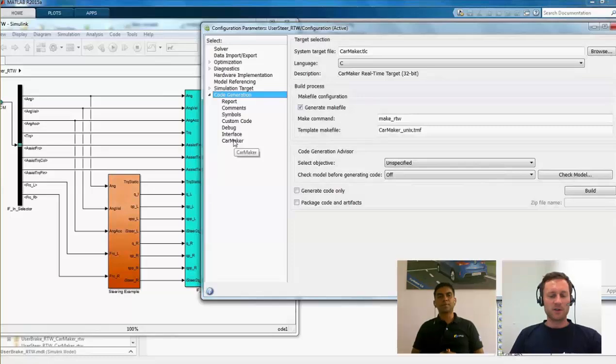Okay, yep. As you've said, you're using Simulink Coder, and with these TLC files, this is basically an instruction set for the code generation. You could also run with a default TLC file that is provided by Simulink Coder, and it creates ANSI C code, so ANSI ISO compatible C code. And with the TLC files, this is exactly what CarMaker has done, you can customize the resulting code to your needs. Exactly. I think these codes can be customized for different applications.